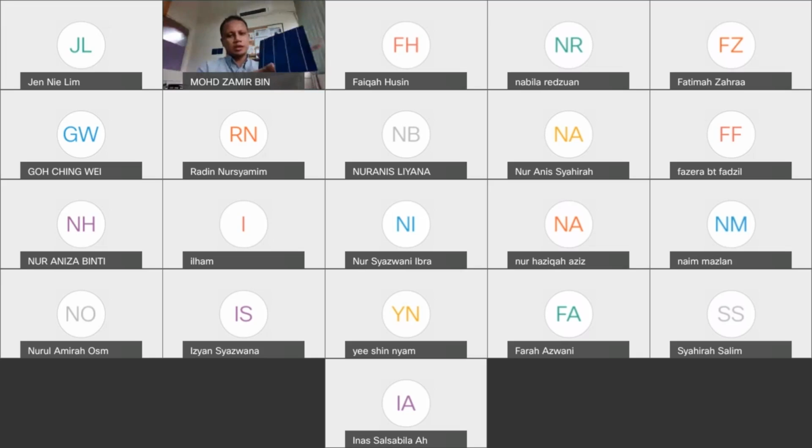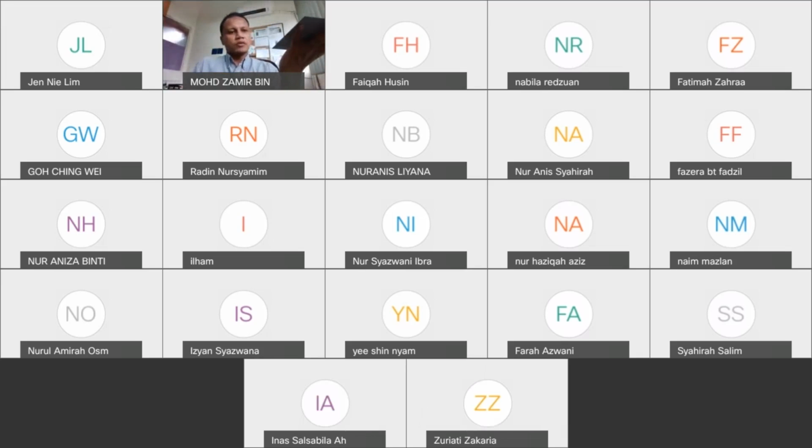You're gonna have 60 to 70 of these in one solar panel. Each panel normally contains 60 cells or 72 cells, the common ones, right? If you have 60, then it's 12 by 5. If you have 72, then it's 12 by 6, right? So this one is a silicon wafer used for solar cell fabrication.